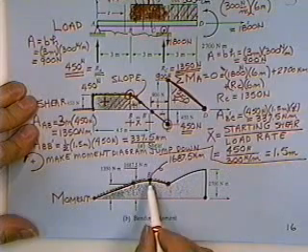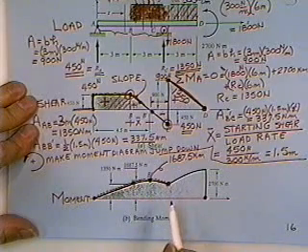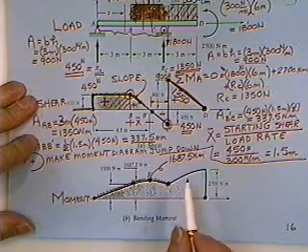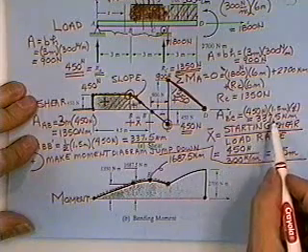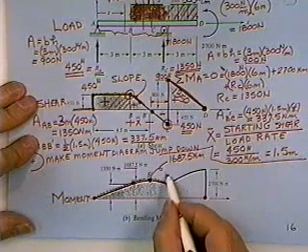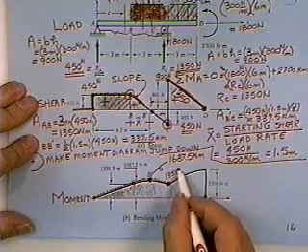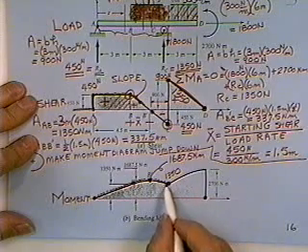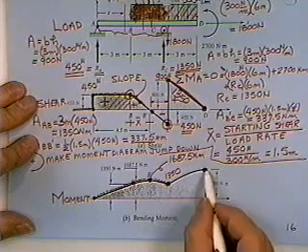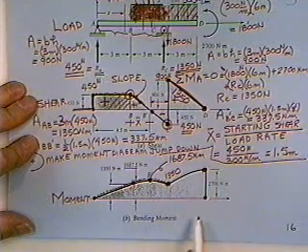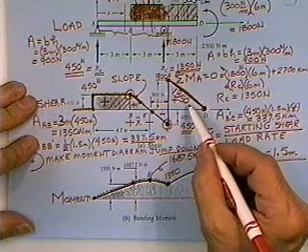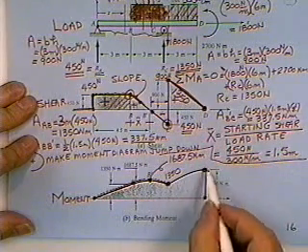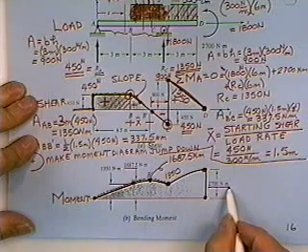As we go from B prime to C, we will subtract an area from B prime to C. That area was listed as 337.5, so we're back to 1350. As we go from C to D, we add another 1350 area from the preceding diagram. 1350 plus 1350 puts us 2700 above the line.